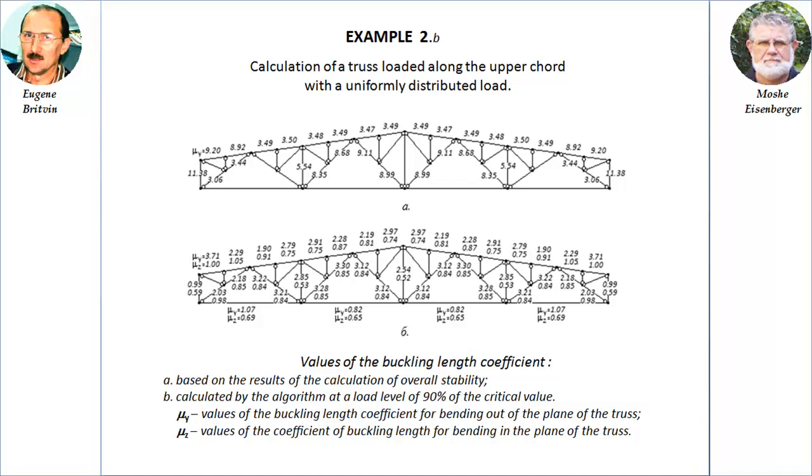Thus, the speed of the algorithm described above is ensured by the fact that, as demonstrated, the boundary conditions at both ends of each element can be obtained by inverting a very small portion of the overall flexibility matrix of the structure. As well, it is shown that to solve the problem, not the entire flexibility matrix is needed, but only that part of it that lies within the band structure of the system stiffness matrix. An effective method for generating the desired band of the flexibility matrix is proposed.